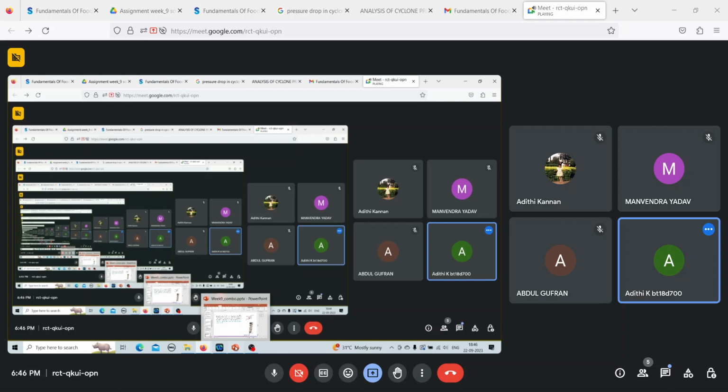So the small differential pressure that this region is experiencing is equal to the differential dFc, the centrifugal force that it is experiencing, divided by area, which is equal to rho omega square r into dr. So here I am substituting the mass dm as rho a into dr. And then if I divide it by area, substituting dm here, dFc will give me rho a dr into omega square r.